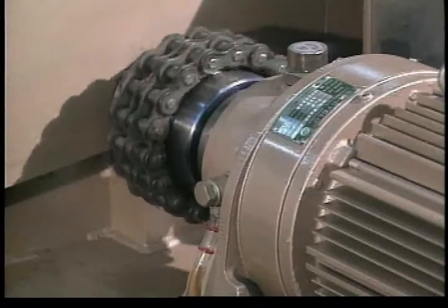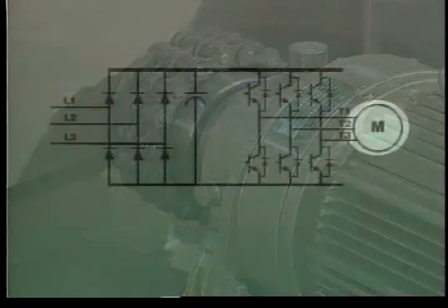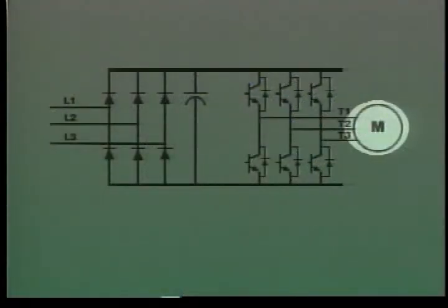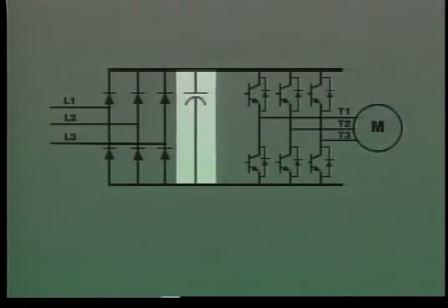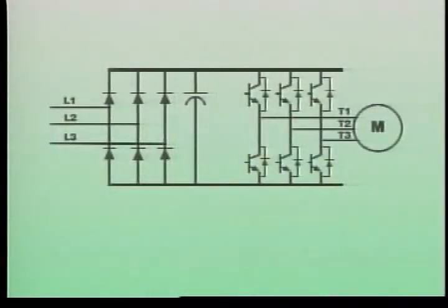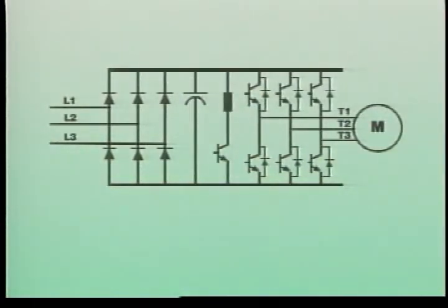With no current being applied to the stator, the turning rotor acts as a generator, regenerating current that is fed back to the capacitors in the inverter. This drains off the energy of the turning rotor, stopping it quickly. If the capacitors cannot absorb all the energy of the rotor, the inverter will switch a resistor into the circuit to help dissipate the energy.